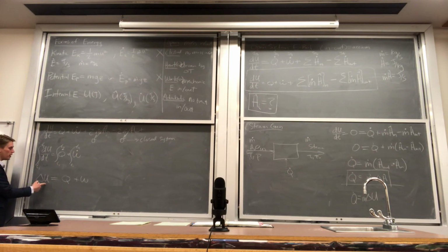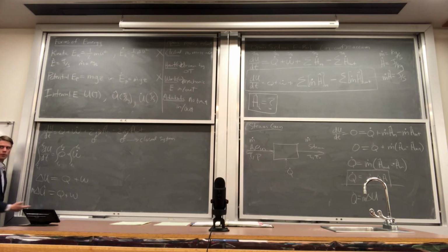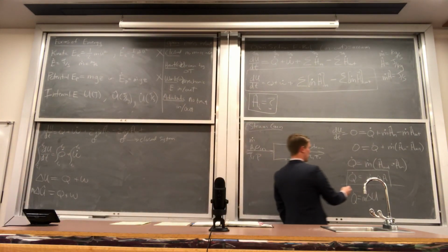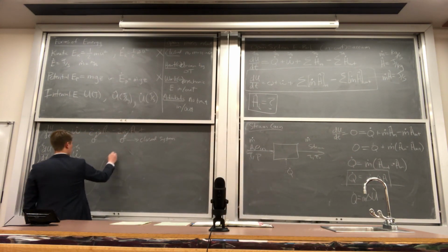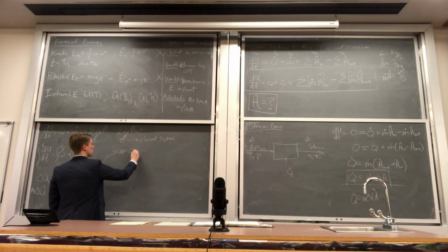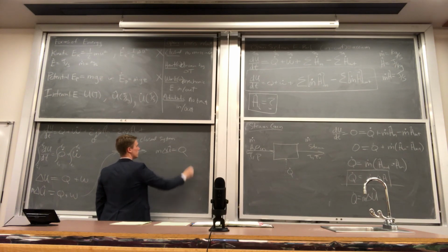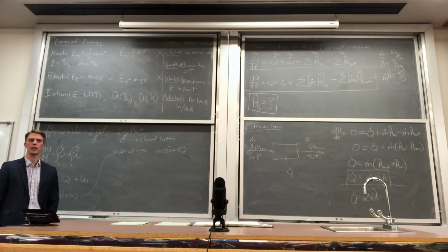So now this internal energy here, you can also rewrite as the mass of the system times some average internal energy. And we get m delta U is equal to Q plus W. We're not exactly at the same expression that we had here, partly because I need a little hat on that equation. But in order to get that expression, we can split it into two ways. If work is equal to 0, then m delta U is equal to Q, which is the closed system energy balance that maybe an introductory thermodynamics class would like to have you memorize.